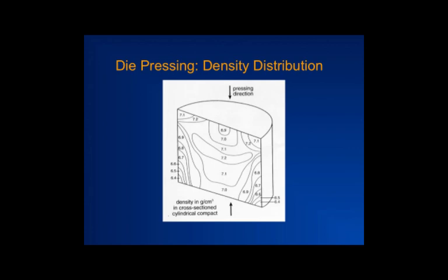And so what happens in practice is components that are made in this manner are never really sintered to full density. They are only sintered to a fraction of full density. You will go from 60% dense when it's pressed to about 90% dense, and you'll have very minimal shrinkage, maybe less than 1% or so, because you cannot afford to have that type of large shrinkage in all directions, 15 to 20%, as we will see in the case of melt processing with injection molding, where it can be a lot more uniform if you do it correctly.